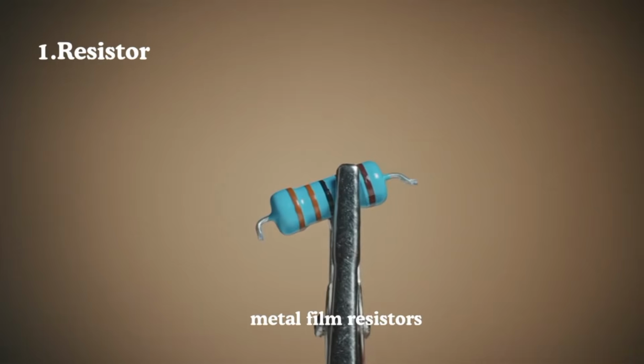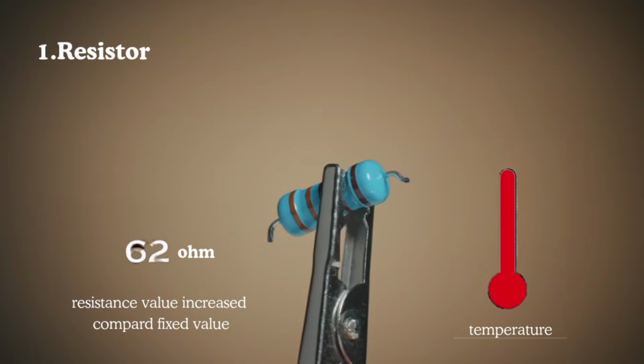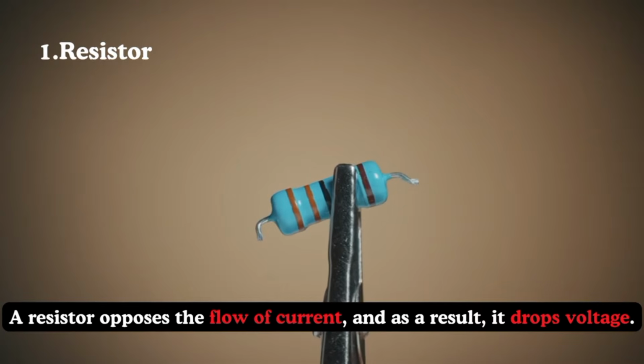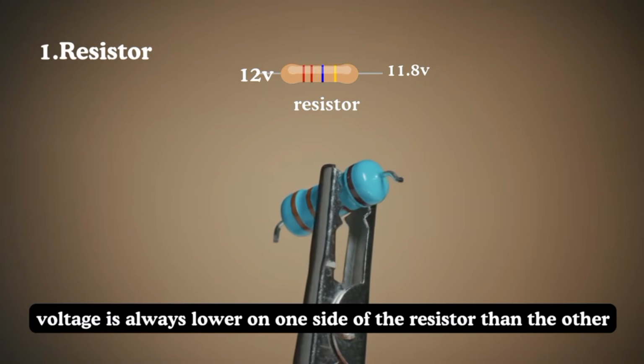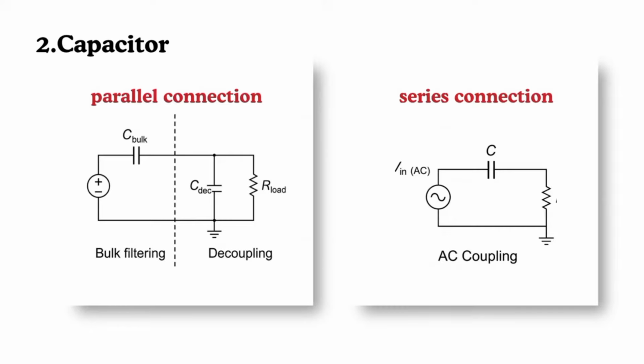1. Resistors. In most metal film resistors, resistance actually increases with temperature, compared to their fixed value. A resistor opposes the flow of current, and as a result, it drops voltage. This means voltage is always lower on one side of the resistor than the other. That's how it converts electrical energy into heat.